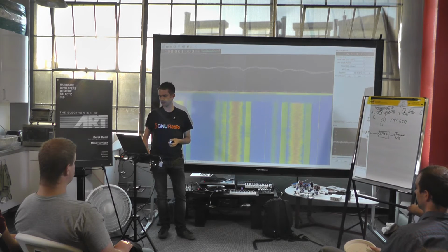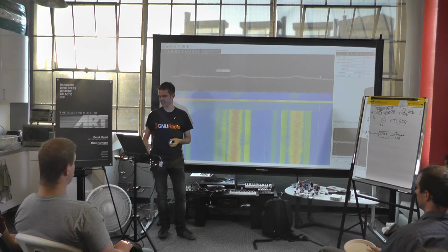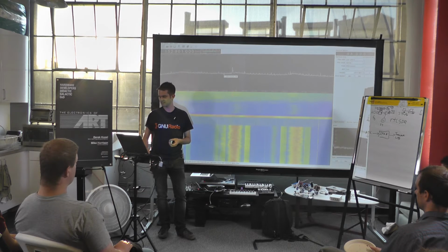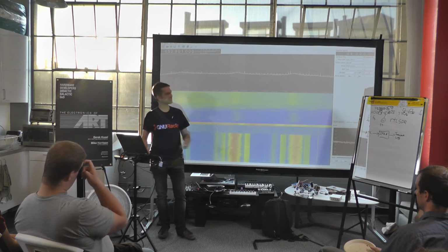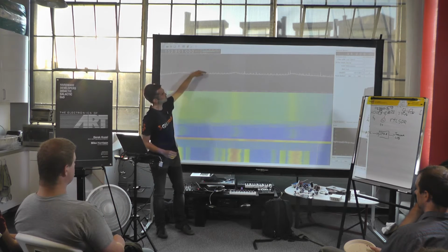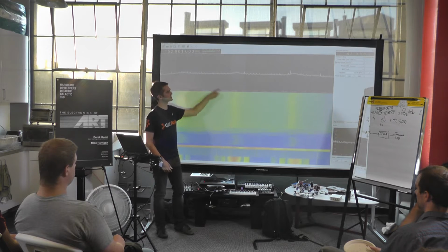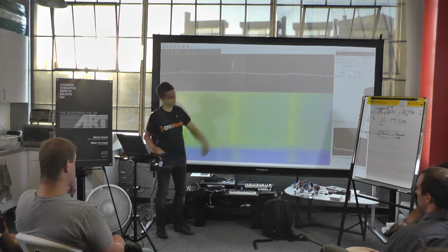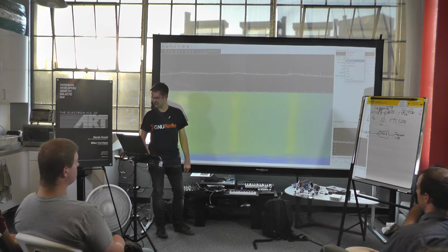So if we go to about 150, if we're a little lucky, we'll actually see public safety FM. Oh, there we go. So that's a public safety radio right here. Sorry, I skipped ahead a little. This is showing intensity at a certain frequency. So where this red spike was, you could see it there. Yeah, there we go again. So they're transmitting. And I can actually change this so that we're getting, let's go with upper sideband, just a much smaller receiver. And if they transmit again, we'd actually be able to hear it.